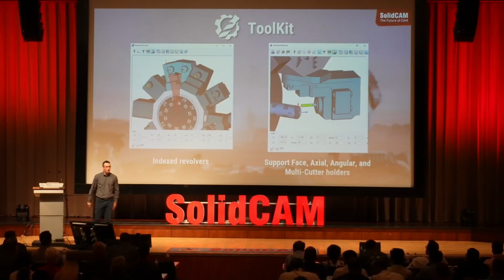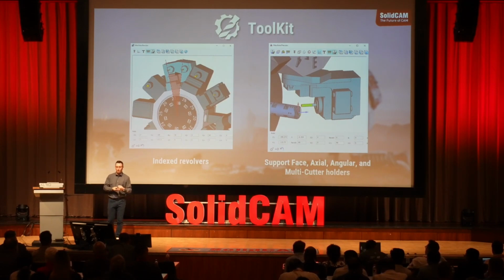When I say that, it's not only to have a holder, position the tool, and create a toolpath, but also all the things behind the scenes. Handling planes, handling arc interpolations, handling compensations. All this is going to be configured with the post-processor. So the user is going to get what his machine really expects to get.